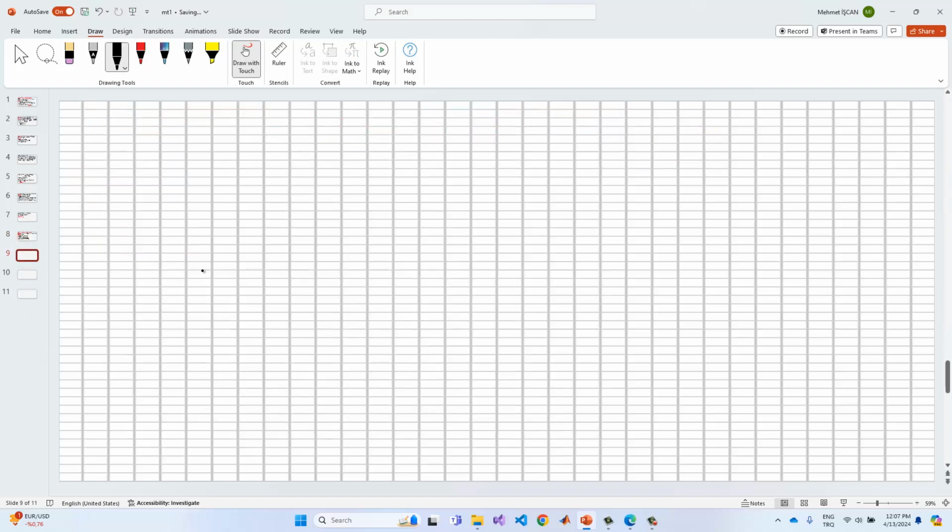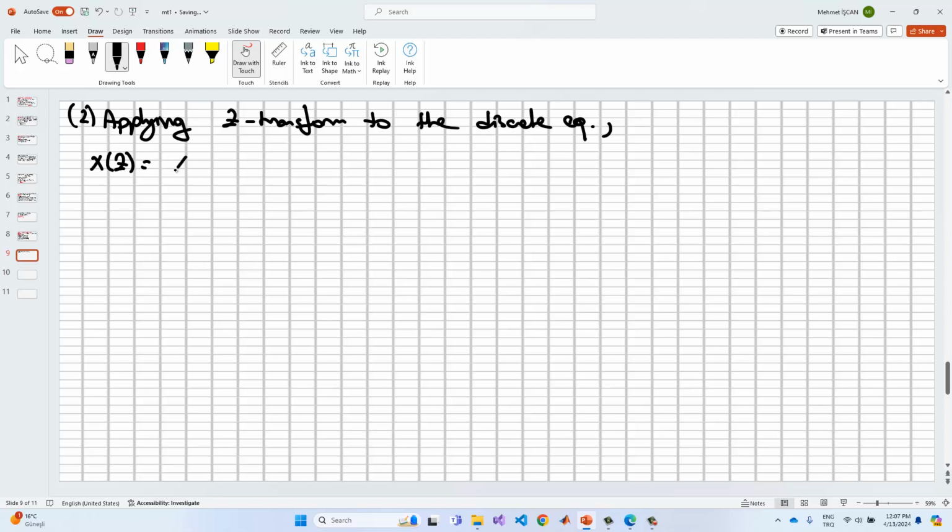So if we have this information, then we can apply Z transform in here to the discrete equation, and then we get X(z), this is the k term in here, and X(z) times z to the minus 1, because we have the k minus 1 in here, times (1 minus dt times a), plus z to the minus 1, because we have the u[k minus 1] in here, U(z) times dt.